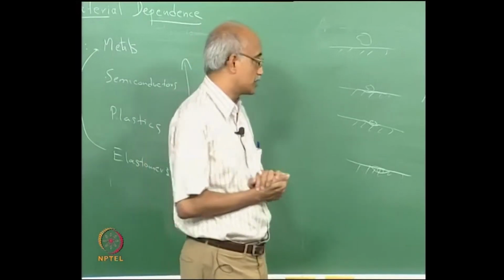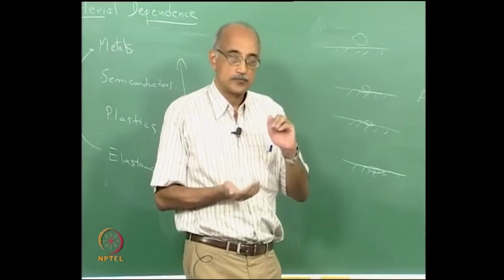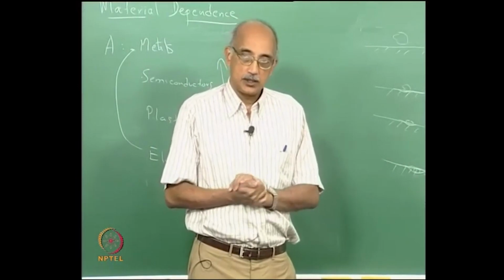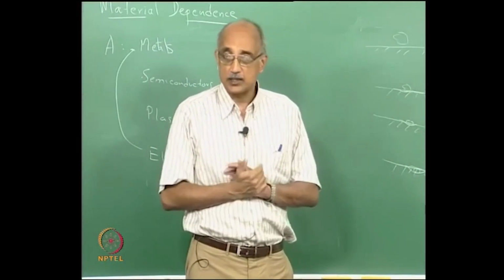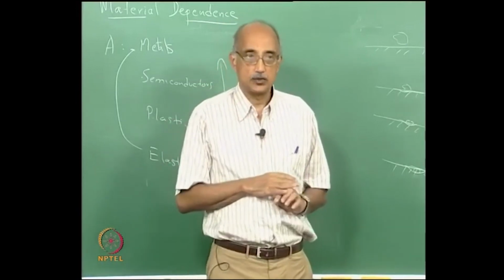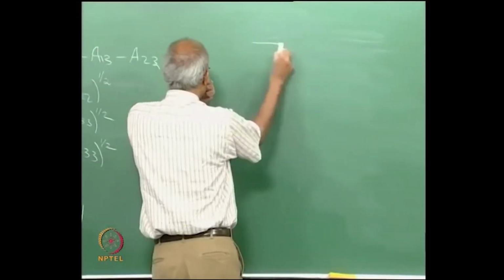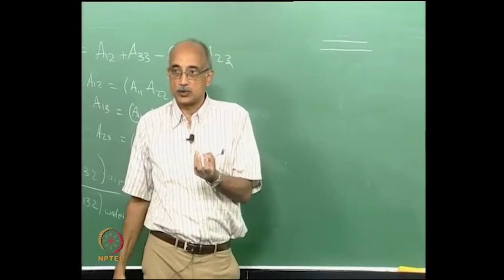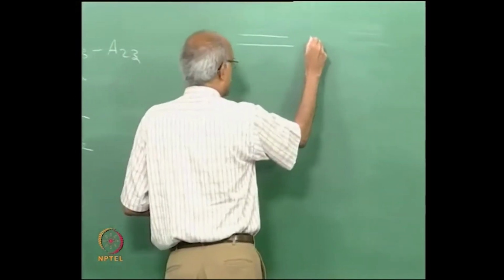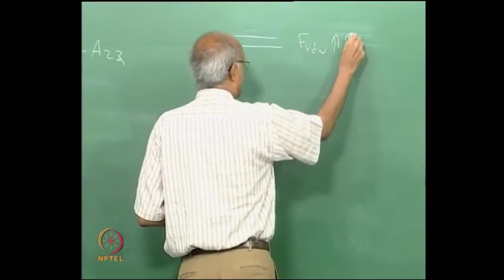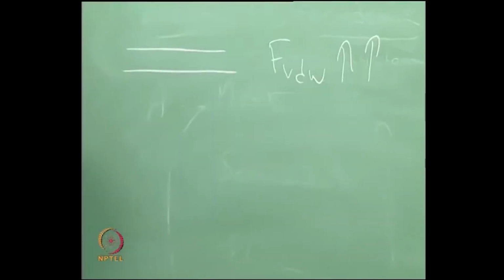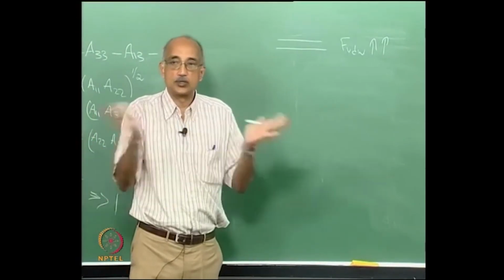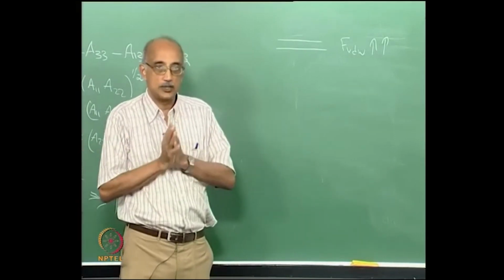And in fact, some of the same arguments apply for roughness also. When you have two smooth surfaces contacting each other versus two rough surfaces, again the adhesion forces are different, and the reason for that again is the differences in the area of contact more than anything else. So when you have two smooth surfaces that come in contact or a highly polished particle that is approaching a surface, the van der Waals force is very high. In fact, I'm sure you have heard of the experiment where you bring two highly polished surfaces together, you can almost never take them apart. The forces of adhesion are virtually infinite.